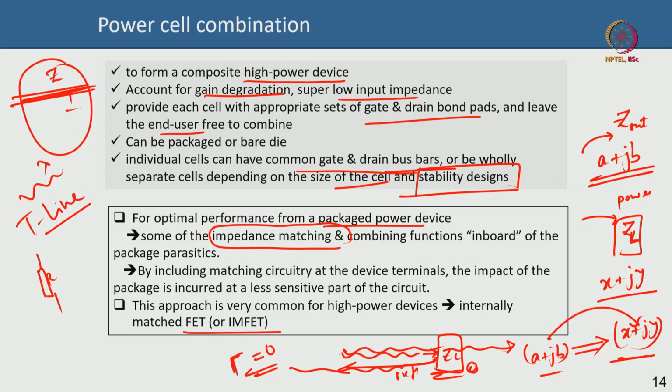Okay. So that matching circuit is needed to actually make a power amplifier, so that your reflection is minimum, you transfer the maximum power to the load, or you have the maximum efficiency or gain. So that matching network could be inside the package, which means you have a discrete die and this is your package. Suppose inside the package you attach the die, the die means the discrete transistor, multi-cell could be, and then you have the matching network implemented within the package.